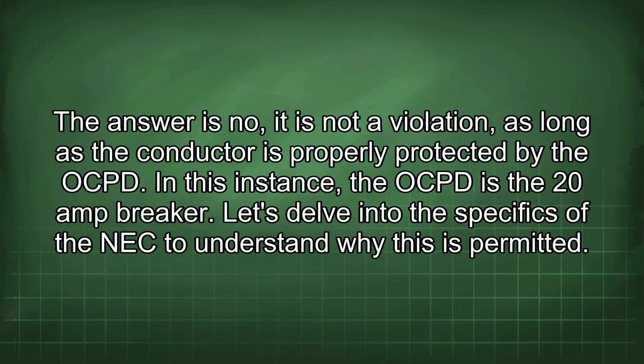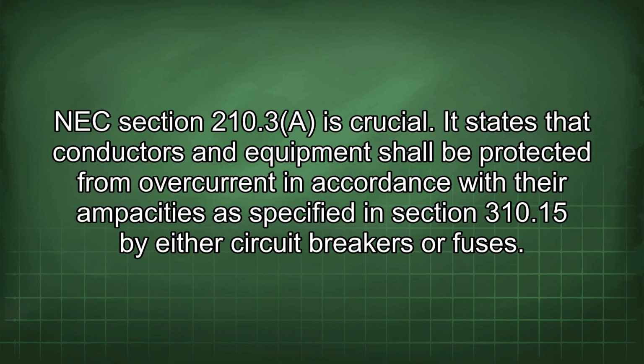It is not a violation as long as the conductor is properly protected by the OCPD. In this instance, the OCPD is the 20-amp breaker. Let's delve into the specifics of the NEC to understand why this is permitted. NEC Section 210.3 is crucial.